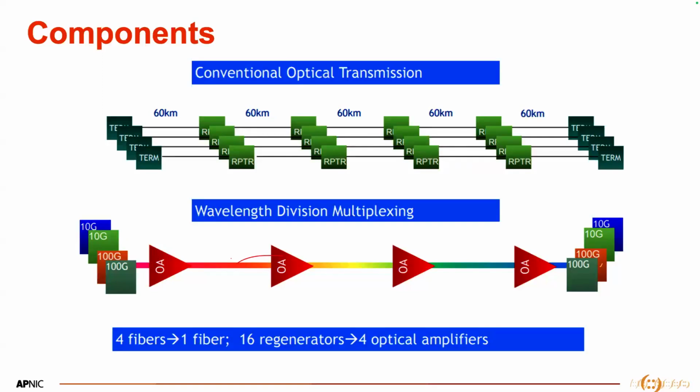There you will get a visible idea what OSNR is going to be there for each and every lambda. You want to keep the OSNR as high as possible, because your lambda card will say which lambda should have what kind of OSNR. So your lambda card will have the threshold in itself.